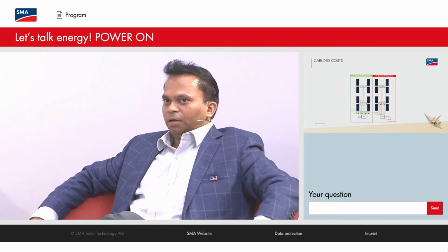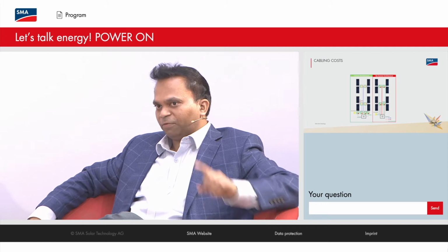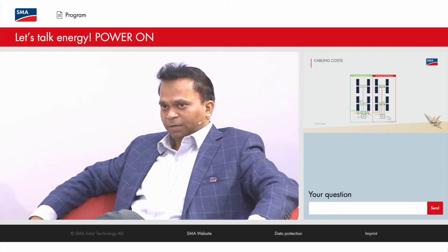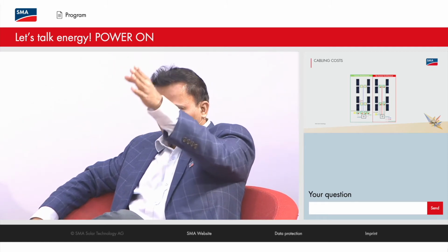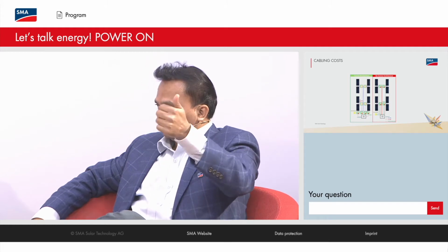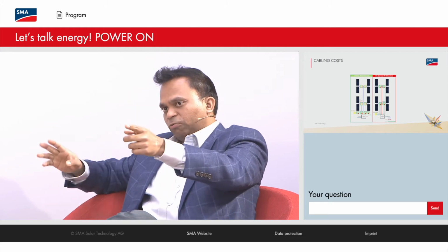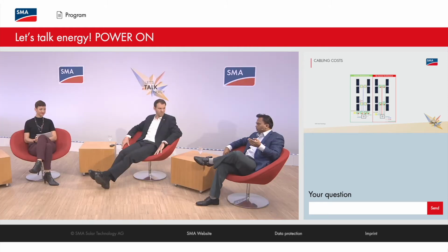On top of that, I can quickly discuss very clear cost advantages in terms of cabling costs. You see that, as I explained, the DC cables that you see in the middle are 2 runs, one positive and one negative. For the same length, the AC cables on your right in red are 4 runs if they have an anti-PID solution.